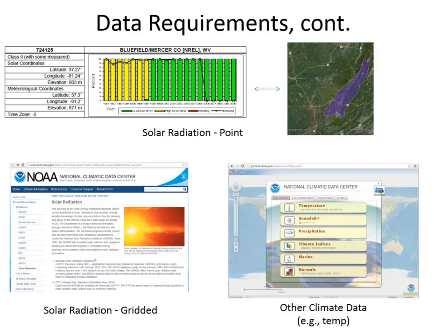Remember, it would be really a bad practice to try and predict what happened in terms of precipitation in here with a rain gauge that far away, but it's not so bad to estimate how much sunshine there is based on a radiometer that far away from a watershed, because solar radiation doesn't vary spatially as much as precipitation does.